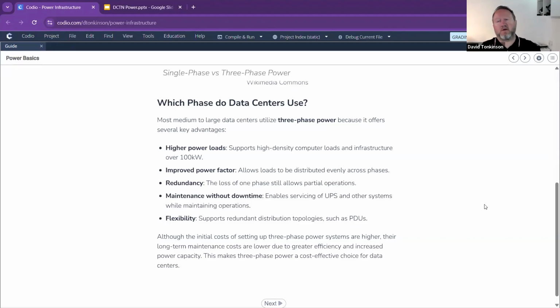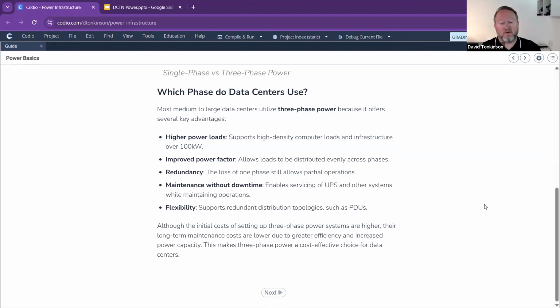Well, the initial key challenge within a data center is basically with the devices that you're putting in. The majority of servers and the majority of technical equipment is still running off of AC with its own individual transformer. So you have to physically go out and purchase those items that do support DC directly. That's really one of the big ones. Triple phase means that we get redundancy, which is where AC is better to a certain extent.